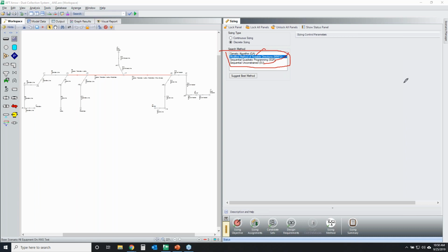Let's say also that the current pipe size I'm using for the initial input could also potentially make an impact on design. So if I'm using different sizes versus making everything be 12 inches in diameter, where you start your initial pipe size guess in the model input could potentially have an impact on what your resulting pipe sizes might be.